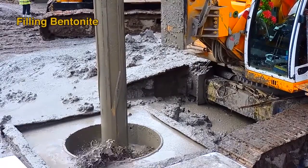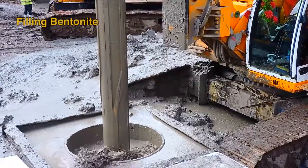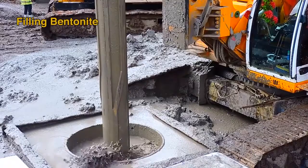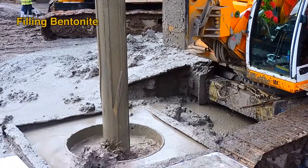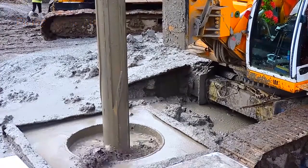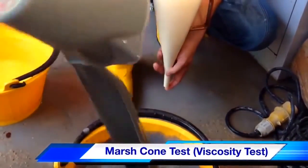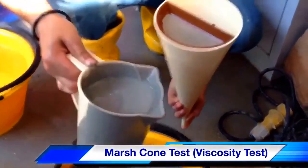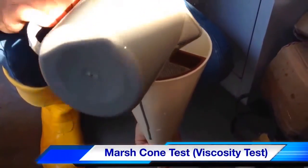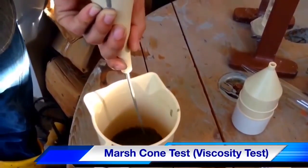It remains in the excavation and does not flow to any great extent into the soil. Further, it can be reused after separating sand by the use of separators called desanders. Bentonite properties such as density and viscosity should be checked. When the piling operation is going on, properties of bentonite should be checked from time to time. Viscosity is one of the major properties of bentonite which directly affects the circulation of bentonite.